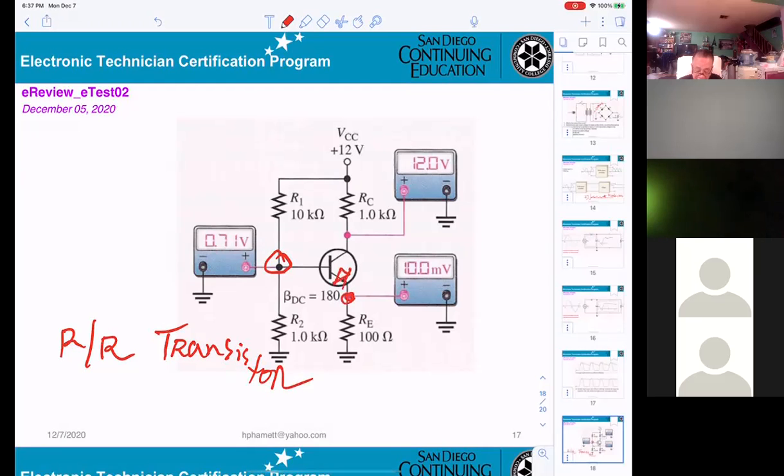That means you still get voltage here, whether it's wrong or right, it doesn't matter. However, when you get 12 volts here, and 12 volts here, there's a short or open somewhere. Normally the resistor will be open, not short. So that only tells you one thing, the transistor is not working.